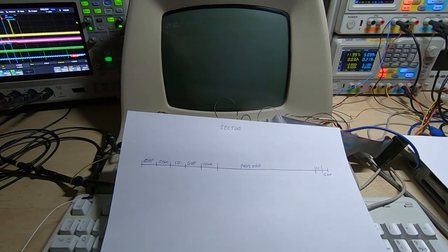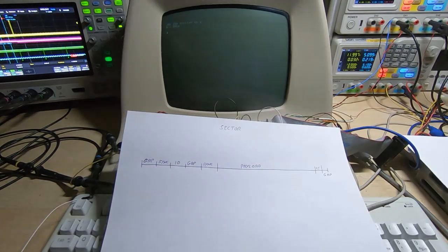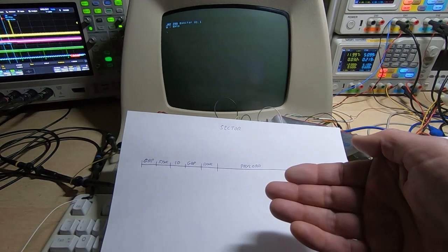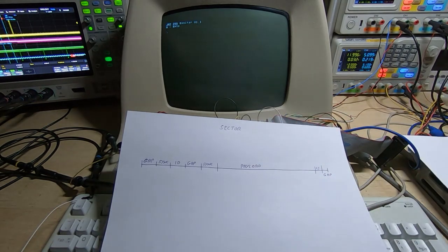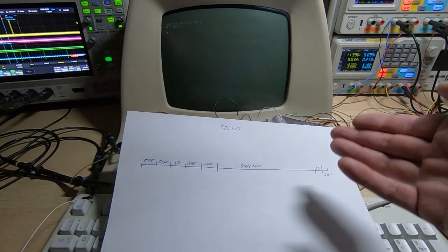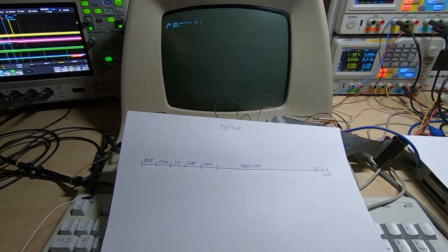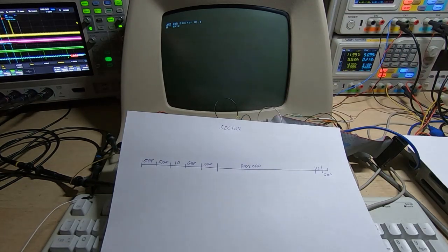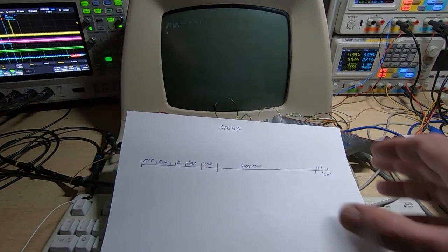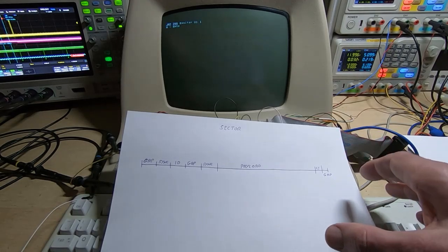That brings us to the first complication if you're trying to work on a floppy drive system. If you have a single machine and it has 2 floppy drives, for example, you take one disk and put it into drive A and stream all the data from it, and then you take the same disk on the same machine and put it into drive B, stream all the data, you might find you have slightly different data streams coming off the 2 disks, because the 2 drives will most likely be performing slightly differently, and that can cause some confusion.